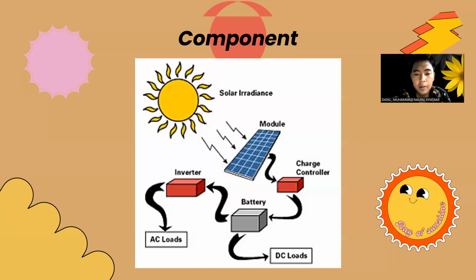When the voltage drops to 11 volts, the controller will charge the battery with the solar panels as a power source. Of course, the charging process will occur when there is sunlight. If the voltage drop occurs without sunlight, the controller will cut off the supply of electrical energy.